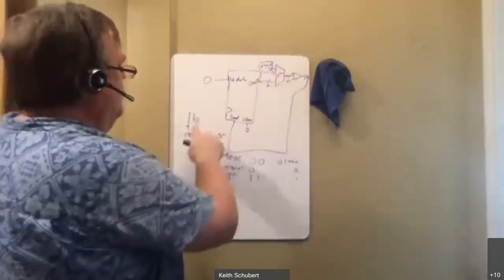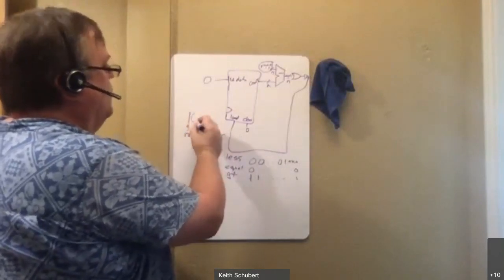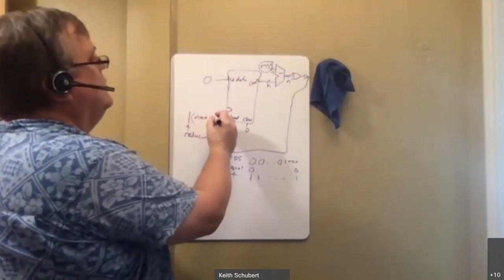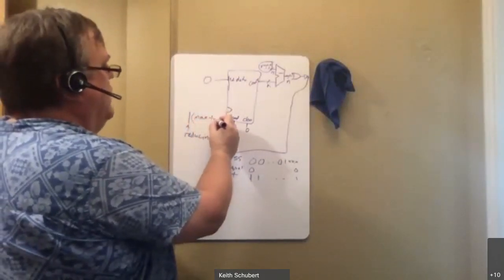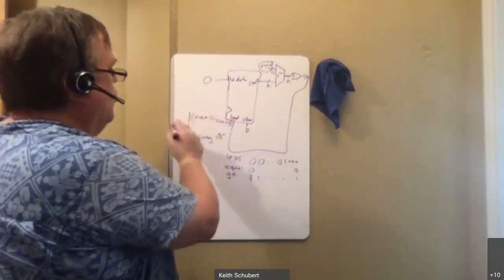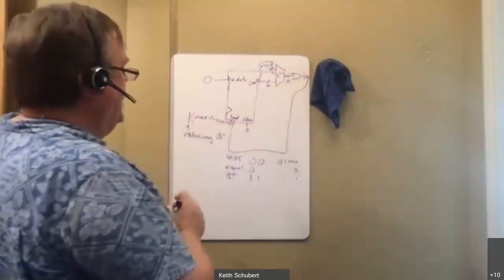So if I took the output of this subtraction and I reduced it, right? I can take this OR, put in parentheses, and I got a max minus 1, minus my count, and then I ORed it, that will do that subtraction and do a reducing OR, basically build that.